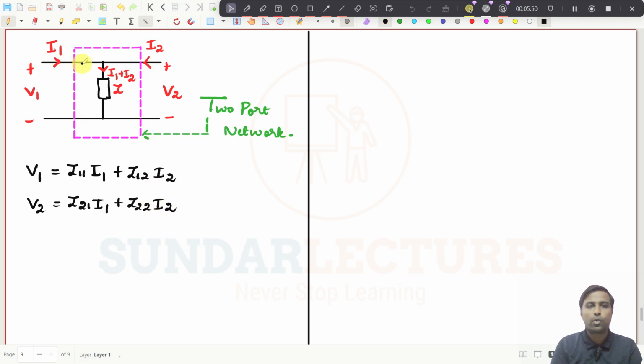See what we will do, we try to write the KVL for this particular loop. This is a loop, right? If you apply voltage here, then this becomes a loop. Make this circuit open circuited, and you don't apply anything here. Let it be the open circuit. Then if you are writing the KVL expression for this particular loop, you just apply V1 only.